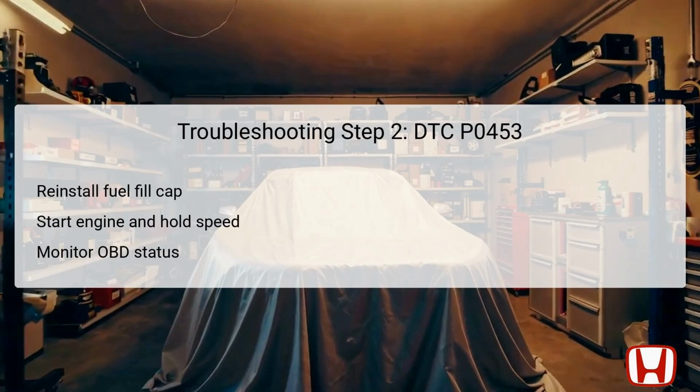Next, you'll want to verify the problem by reinstalling the fuel fill cap securely. A loose or improperly sealed fuel cap can sometimes trigger the FTP sensor to read incorrectly. Start the engine and hold the engine speed at 3,000 revolutions per minute, RPM, without load until the radiator fan activates. This step ensures that various conditions are met for accurate pressure readings from the FTP sensor.